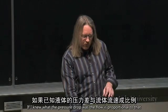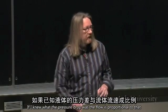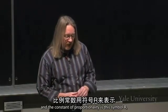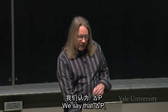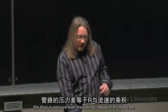If I knew what the pressure drop was, the flow is proportional to that. And the constant of proportionality is this symbol R here, the resistance to flow. So we say that delta P, the drop in pressure over the tubing, is equal to resistance times flow rate. Delta P equals R times Q.